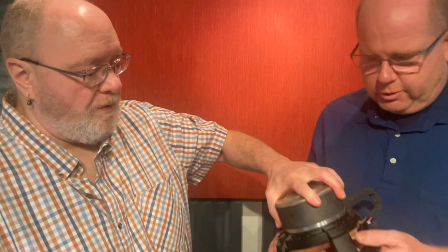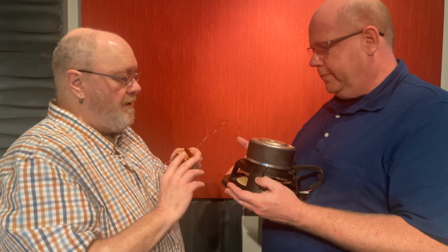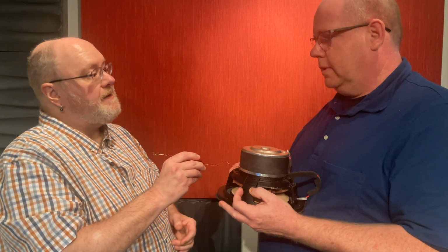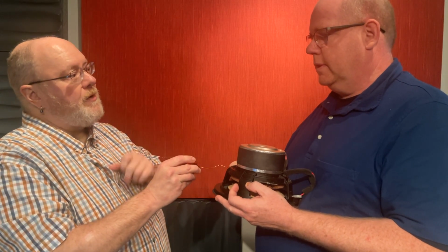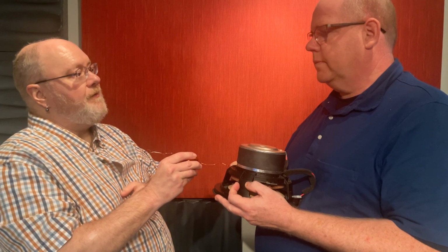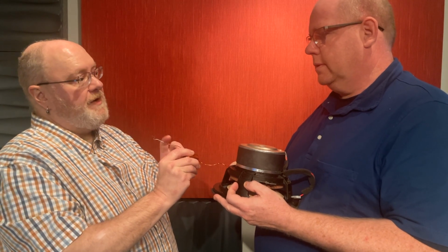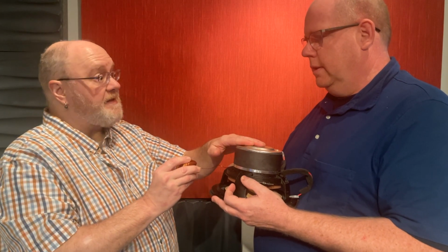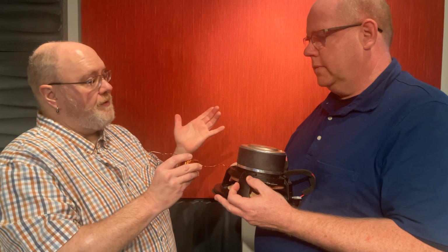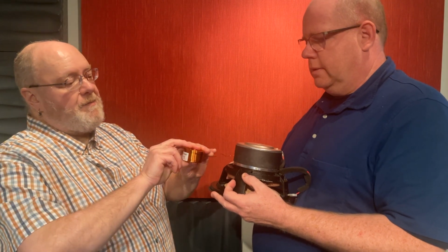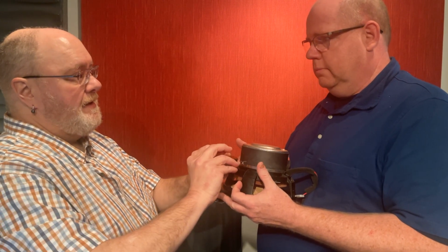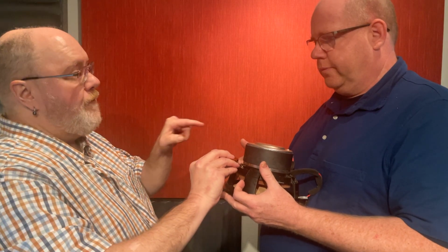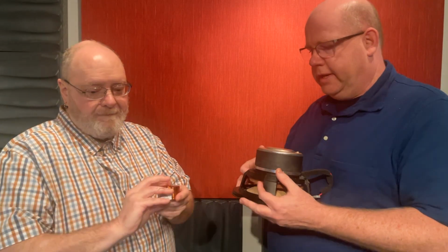Hold the woofer up. I'll hold this, positive here, negative here. If you put that in series, it will allow low frequency information and will filter out the high frequency information at whatever millihenry this is. It will do it at that frequency compared to, say, an 8 ohm driver. If you take that same component and run it across, it takes that same low frequency information that would have gone to here and runs it over to the negative side and shunts it. Once again it gets rid of it.